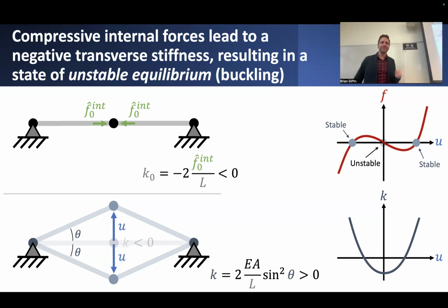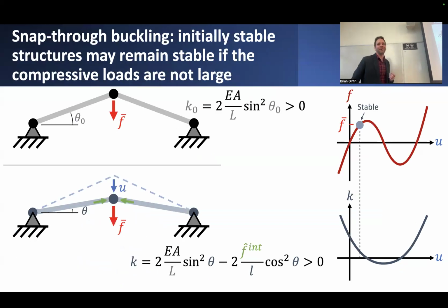That's kind of the issue when you start delving into this domain of, well, I can now simulate these problems that have instabilities inside of them. But even if I can simulate it, should I really be doing this if ultimately I'm setting up a problem that doesn't have a unique solution? Which one do I go with? This is sometimes referred to in mathematics as a solution bifurcation, where it's not that there's just one possible solution, but there may be many admissible solutions. And in these situations, you no longer have a well-posed problem. That's a little bit disappointing.